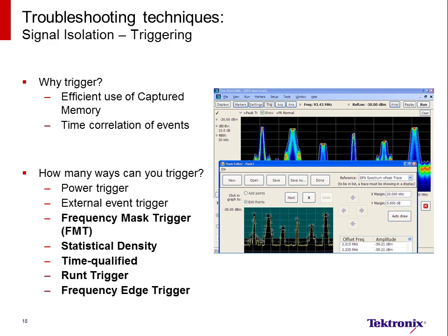On an oscilloscope, triggering is typically applied so that the signal can be stabilized on screen. For long signal acquisitions, triggering is also used to use acquisition memory more efficiently. This is especially true for pulsed RF signals since the off time is rarely of interest and yet is almost always a majority of the signal playback time.